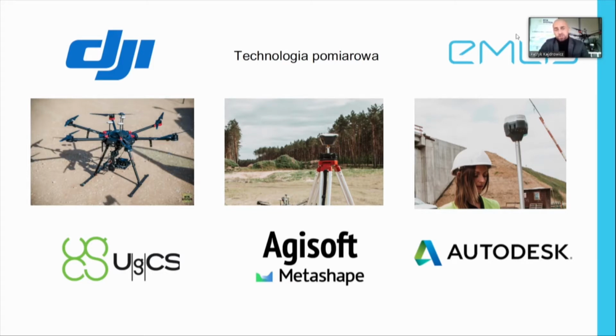And so this is also our equipment for photogrammetry, equipped with a system of accurate data collection, and the base station in the middle photo sending information to the drone, so you will not have to use the reference stations, and the drone position can be identified with the accuracy up to 1 centimeter, and also the receiver on the last photo. So this is a standard receiver for land surveying works. And our system, in fact, does not require setting of points or reference points.